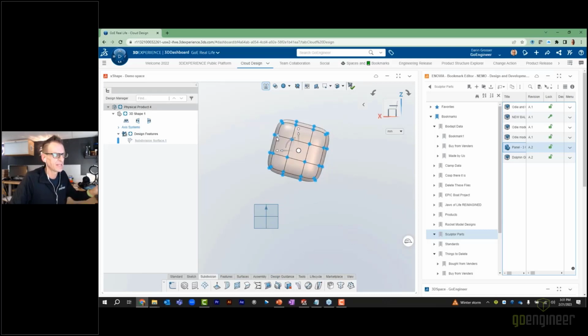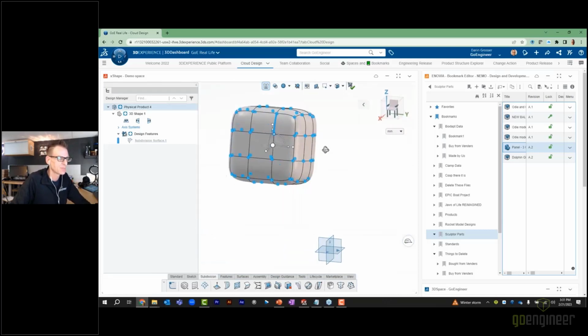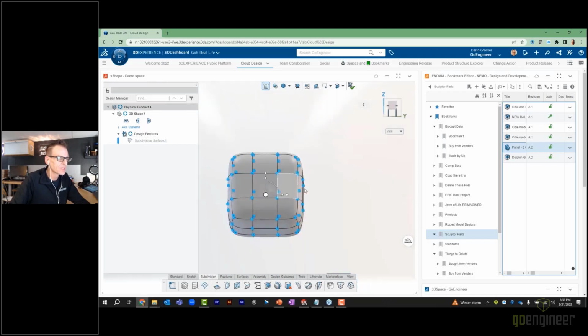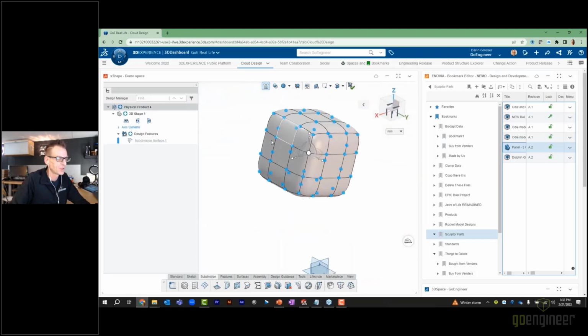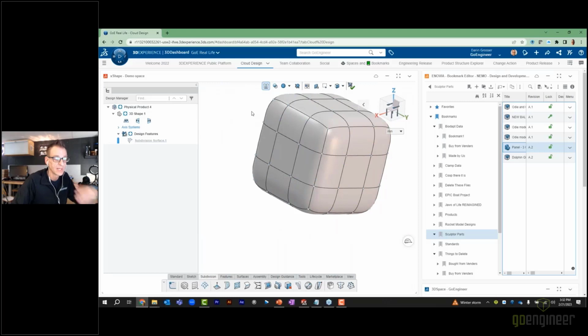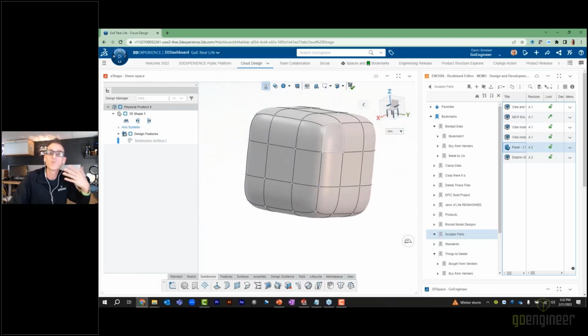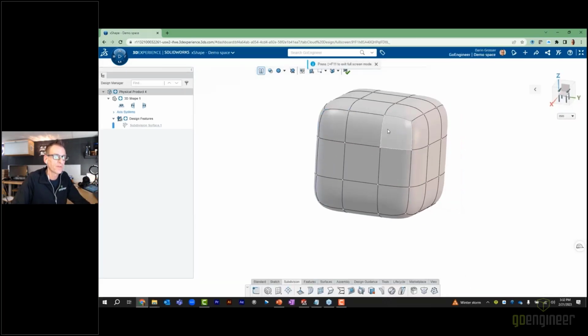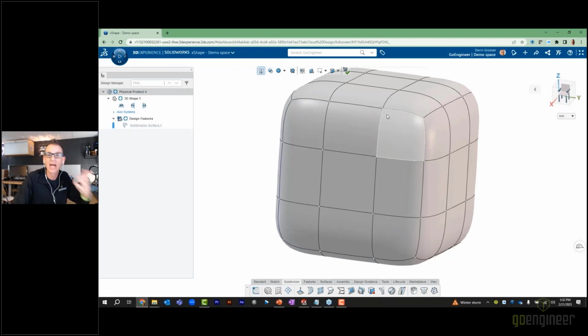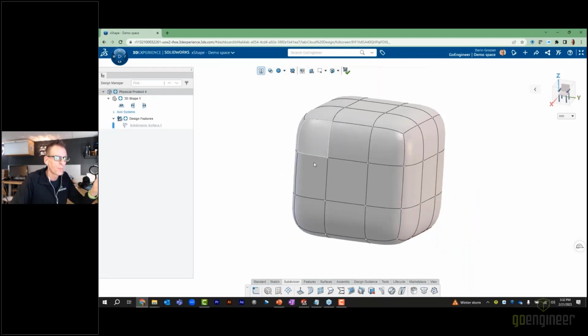Now, for a shape like this, I might start out with, once again, the less is more operation. The purpose of this is I want to have a little bit of a fascia here that's going to be used to house or to mount this panel into. Now, what we're dealing with here is something that's not going to be rounded like we see here. So I want to get a little bit into the tool called crease. A crease is important because it allows us to really emphasize or de-emphasize edges amongst our part. I want to put a crease on this front face, but I'm first going to start with a subdivide.